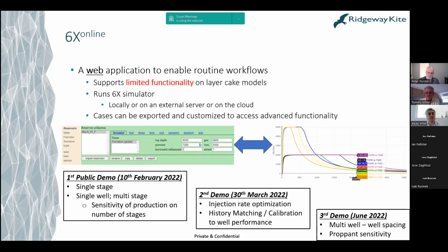The assumption is that if in a particular layer the rock breaks in a certain way at well 1, then all things being equal, it should break in the same way at well 2, the child well, give or take any lingering after effects of the fracturing and depletion of the parent well. So if you have a single well with observations, you can calibrate your model based on that, and it should give you a fighting chance of getting a realistic answer for the second well.